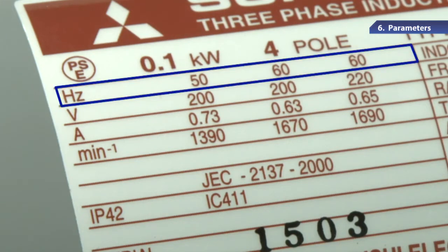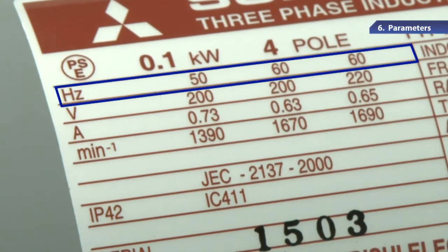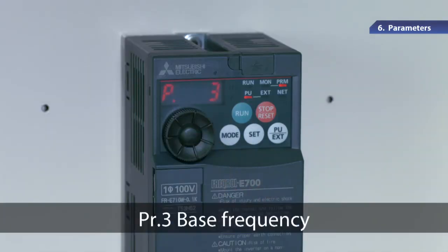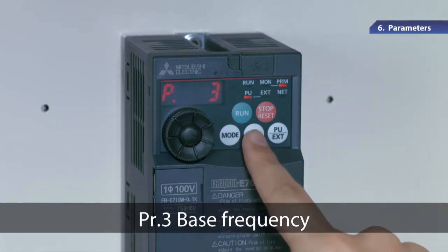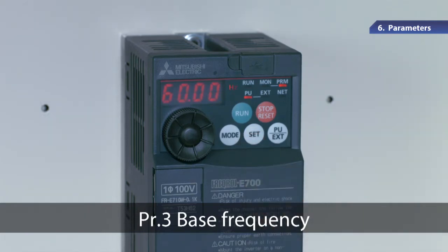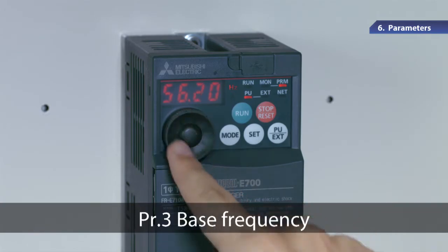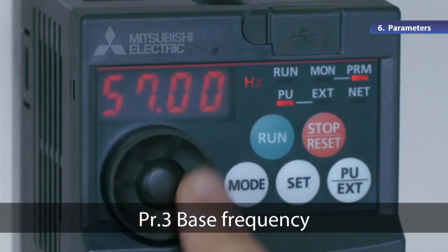Similarly, set the base frequency indicated on the motor nameplate by using parameter 3, base frequency. The initial value is set to 60 Hz. If the value on the nameplate is 50 Hz, change it to 50 Hz accordingly.